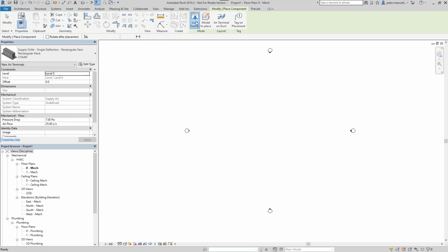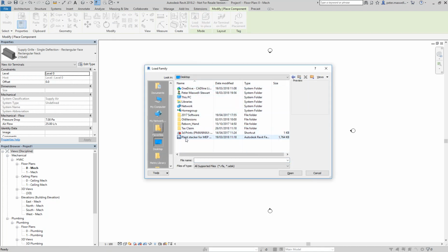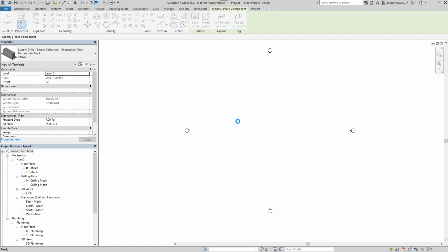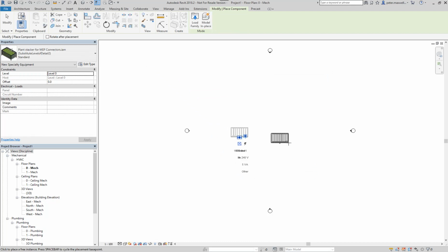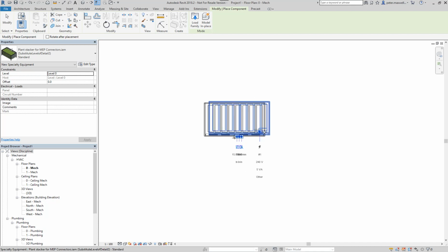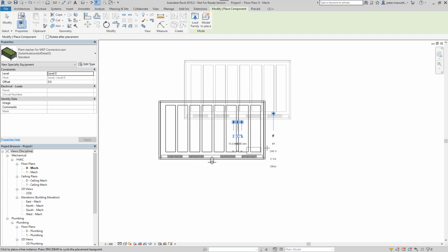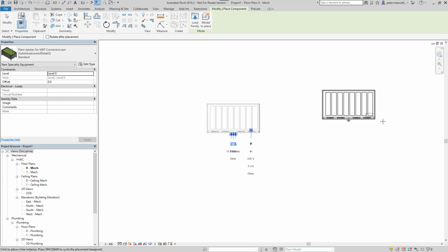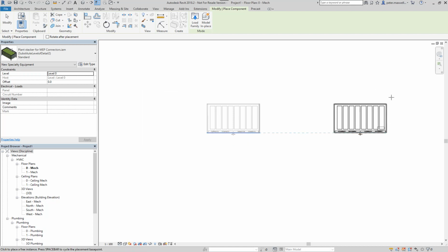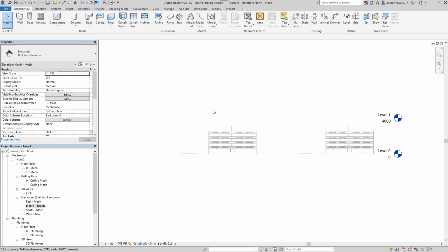We're going to load up one of our connections, or one of our parts, and you see I can place in one of these versions, and automatically you see these little blue connection points here. This is the MEP connectors, this is the metadata that's gone with it, and you can see the values that we filled in have also travelled across. So let's put in 2 of those for now.